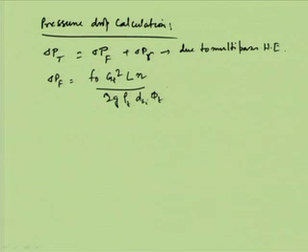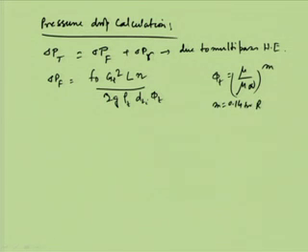Phi T is the viscosity correction. We have discussed that phi T is equal to (mu by mu wall) to the power 0.1m, and this m is equal to 0.14 for Re greater than 2100 and m is equal to 0.25 for Re less than 2100. In most situations, it's in the turbulent flow region, so it is 0.14, and most of the time this viscosity correction factor happens to be negligible. Okay, and it's taken as 1, unity.